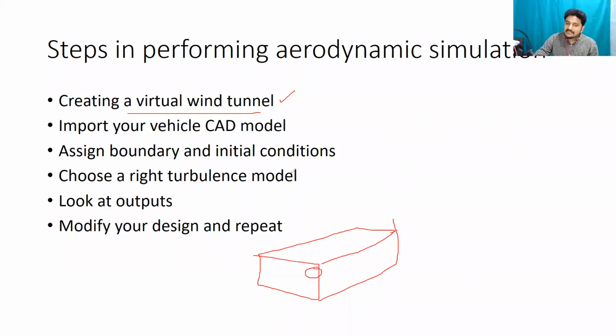And then you assign something called the boundary conditions. So what are those boundary conditions? Well, you can say what is the pressure at this particular face, or you can say what's the velocity at this face, doesn't matter, or the mass flow rate. And then at the outlet, you specify the outflow pressure, right? The static pressure at the outflow.